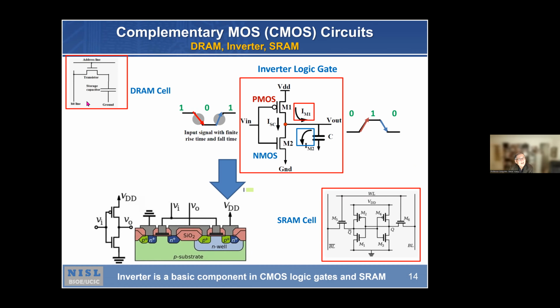And then, we are familiar with the DRAM, which consists of one NMOS transistor with a capacitor. We are also familiar with the SRAM, which consists of typically 6 transistors, 2 inverters back to back, and two access transistors, and the bit line and the bit line bar, for instance. So that's fundamental, the elements in an integrated circuit. And today we have a big market for DRAM as well as SRAM, right?